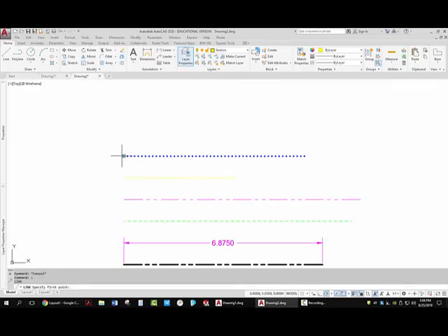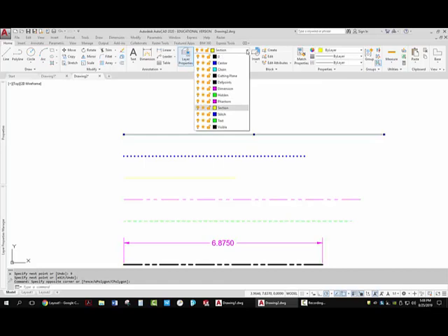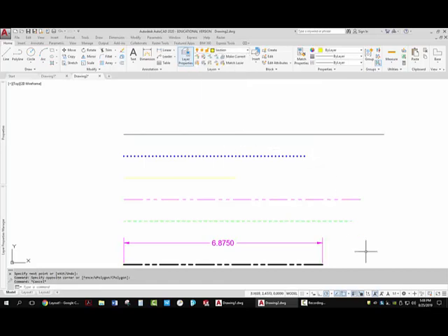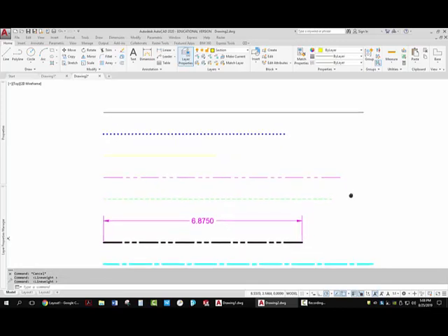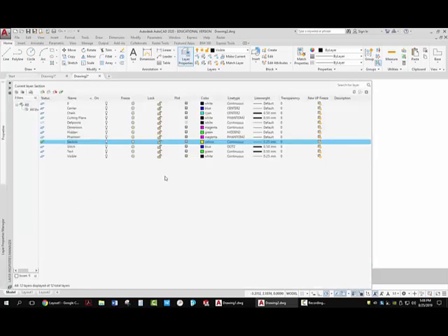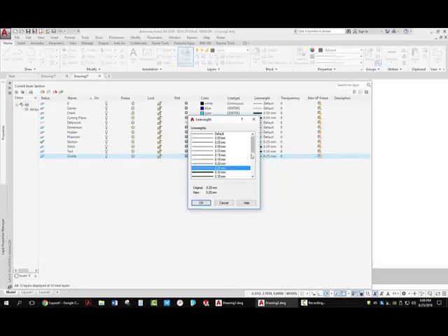The visible line, I'm going to hover here and go up 0.75, and go to the right 9. And just so I don't forget, I'm going to immediately put that on the visible layer. Now that visible line should be thick, and you'll notice if I go to my line weights, the visible line at the moment is not a thick line. So we're going to go back over here, find visible, we're going to change it from 0.25 to 0.5.